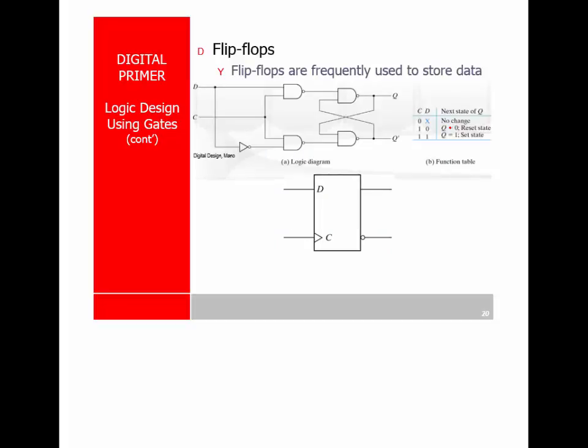Okay, everyone's favorite tiny little circuit right here. This is a typical D flip-flop. Now this is not actually a clocked flip-flop because it does not edge trigger. I don't know how important it is for this class, but in digital there's a difference between a gated flip-flop and a clocked flip-flop.